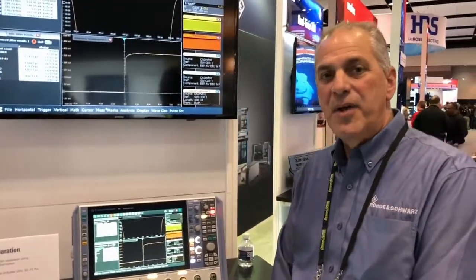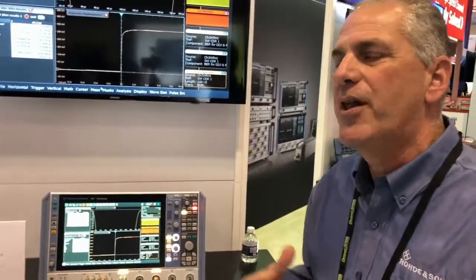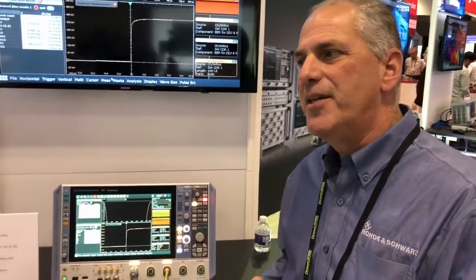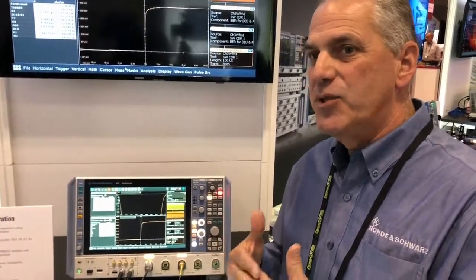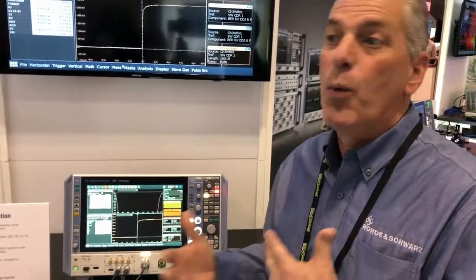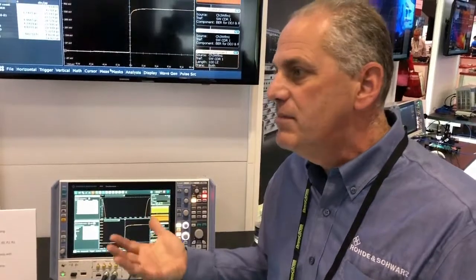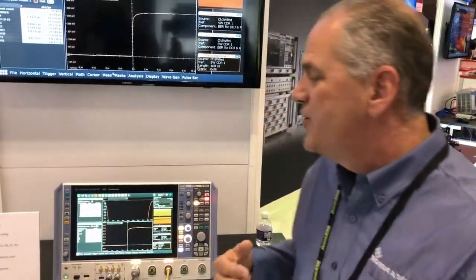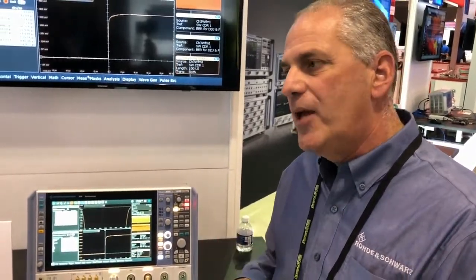Thanks a lot. So here, we're at DesignCon. I wanted to talk a little bit about jitter. So first of all, think about jitter. Jitter is all about bit error rate. The idea behind it is when those edges transition at the wrong time, then a digital receiver can mistake a 1 for a 0 or a 0 for a 1, and then you have corrupted data and it doesn't get to the other end. Doesn't work. So we care a lot about jitter because it is one of the main causes of bit errors in the system. And if you think about jitter, it's caused by two primary factors.